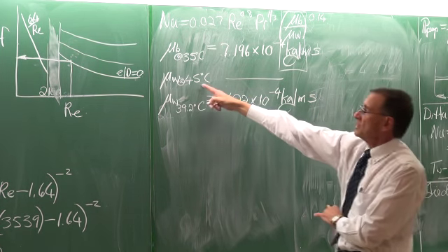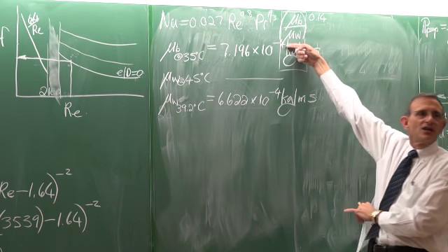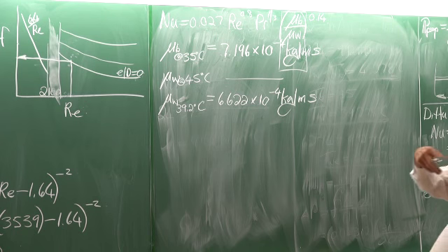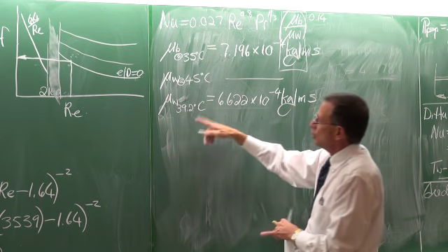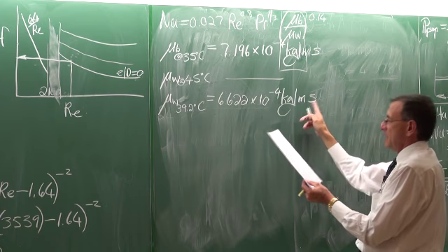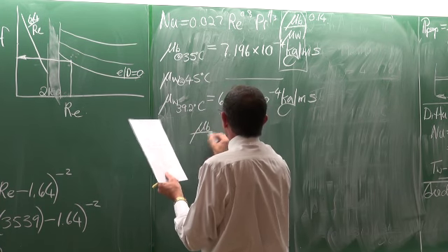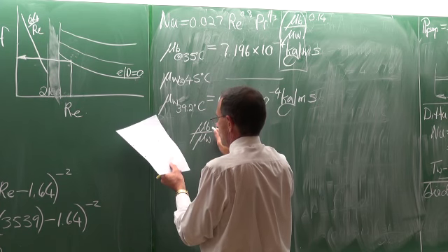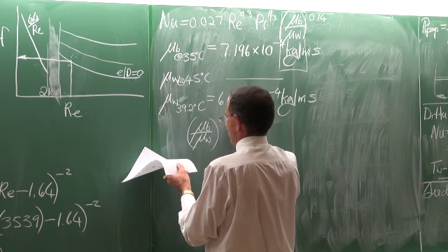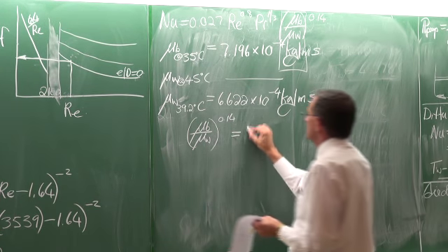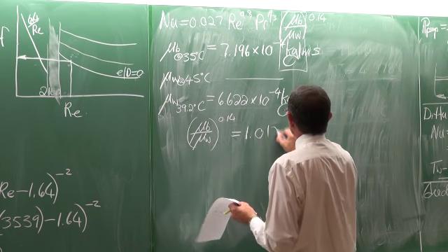So you can start at 45, calculate the Nusselt number, the heat transfer coefficient, the wall temperature. See that you've selected too high, go through it again, and very quickly it will converge to that wall temperature. But the thing that you can check for is the bulk viscosity divided by the wall viscosity to the 0.14, which for this case is equal to 1.012.